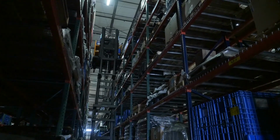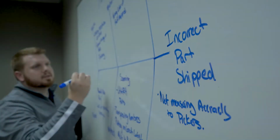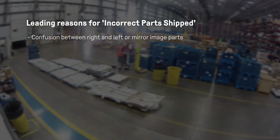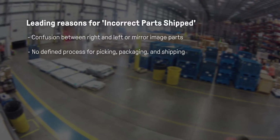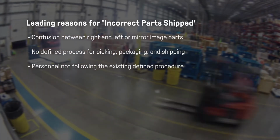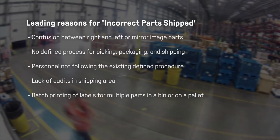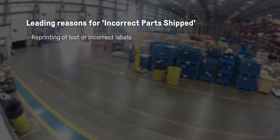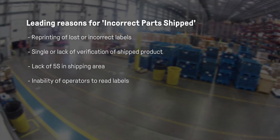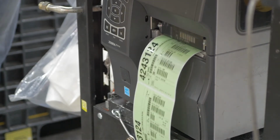Although these simple errors may seem trivial compared to other defects, the results are still very costly. In discussion with companies in our supply chain who have experienced this challenge, and by using root cause analysis tools such as fishbone diagrams, 5 Whys, and is-not analysis, we have ascertained several leading reasons, which include confusion between right and left hand or mirror image parts, no defined or documented processes for picking, packaging, and shipping, personnel not following the existing defined and documented procedure, lack of audits in the shipping area to confirm compliance to process, batch printing of labels to be attached to multiple parts in a bin or on a pallet, reprinting of lost or incorrect labels, single or lack of verification of shipped product, lack of 5S in the shipping area, and the inability of operators to read labels.